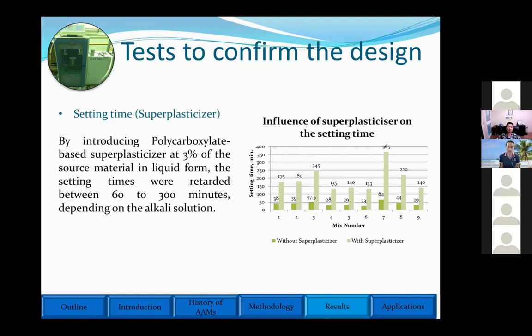So it is good, for example, for shotcreting or for repair of concrete, if you don't want to introduce any admixtures. But for normal concrete, we typically need at least 1.5 hours, because we are supposed to produce it in a plant and then transfer it by trucks to the construction site and then pump it in a desirable area. So we need to introduce some chemicals, some admixtures.